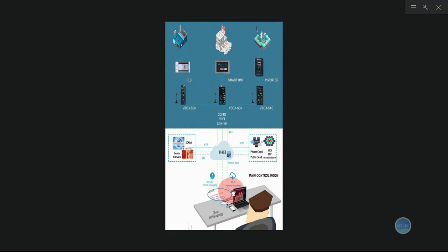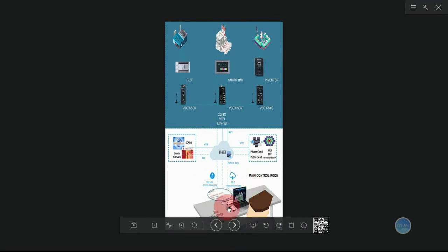But if they go to site, it will take a lot of time and a lot of money. In this way, remote downloading the PLC project becomes so convenient. People can edit their PLC project on their PC, and use the VBox as a medium to remote download to the PLC through the VNet.